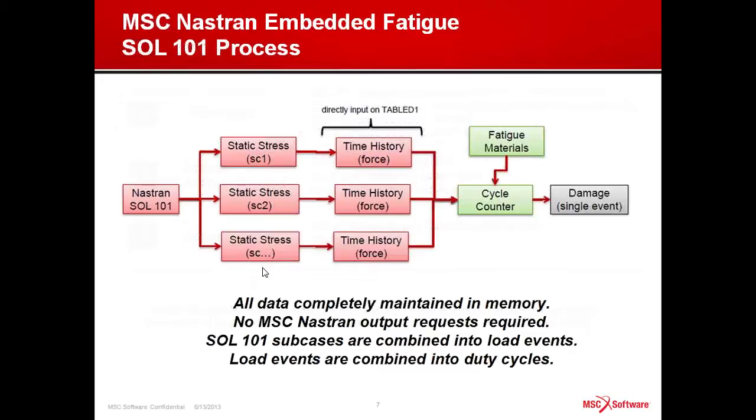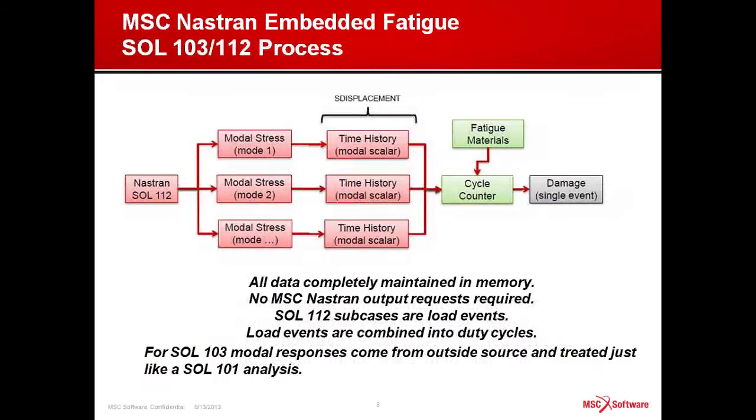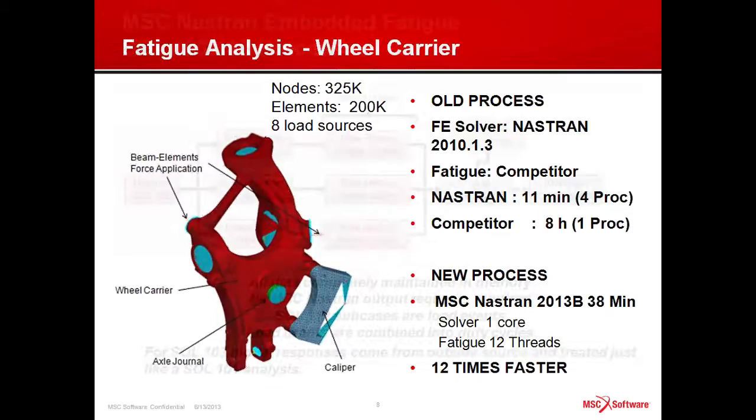The combination of those two things can be combined into duty cycles, and then we do a rainflow analysis to count the number of cycles, combine that with the material data, and use that to predict the fatigue life. A similar process occurs in a SOL 103 or 112 process, where we do a modal extraction, do a stress recovery of the modal stresses, and proceed to do the same type of process to determine the fatigue life of your model.